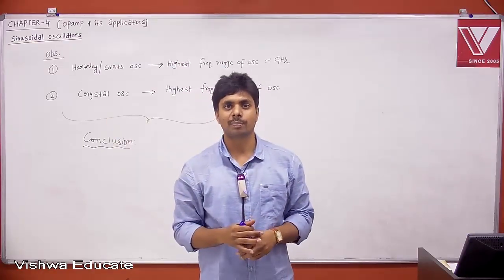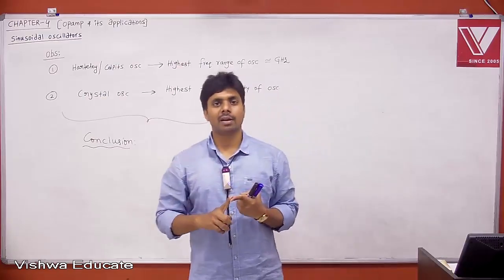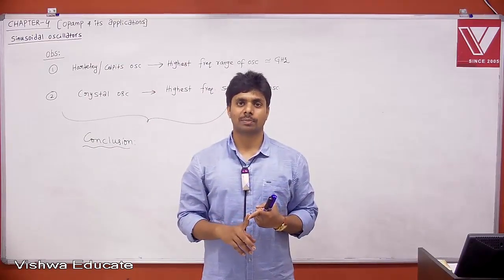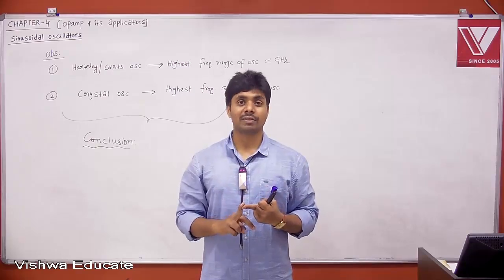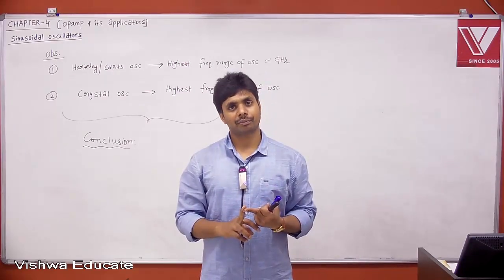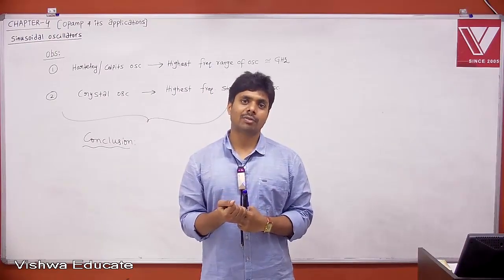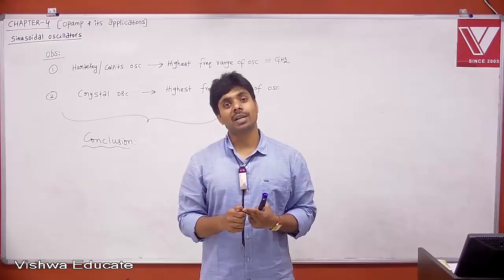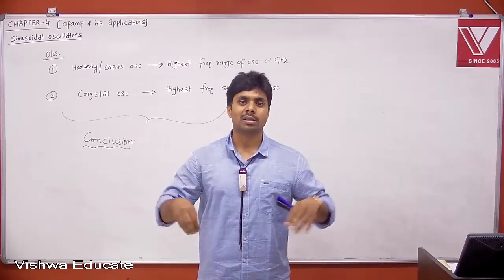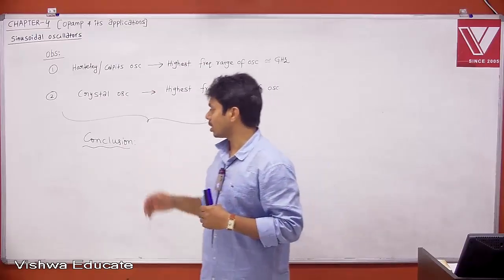That is your best case. In BJT amplifiers, I told you the CE amplifier gives very good voltage gain but no impedance matching for voltage amplification. The CC amplifier gives very good impedance matching but no gain. Then what we did is combine both of them. We got gain from the common emitter amplifier, and impedance matching from CC amplifiers, inserting CC at the input and CC at the output. Similarly, what is the conclusion?